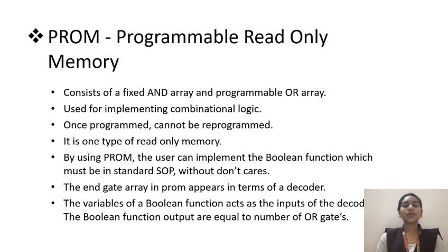Coming to the PROM, which is also known as programmable read-only memory. The PROM consists of a fixed AND gate array and a programmable OR gate array, which means that the AND gate array is fixed and not changeable, and the OR gate array can be programmed at any time. So we can program or recreate the OR gate array, but there will not be a change in the AND gate array.